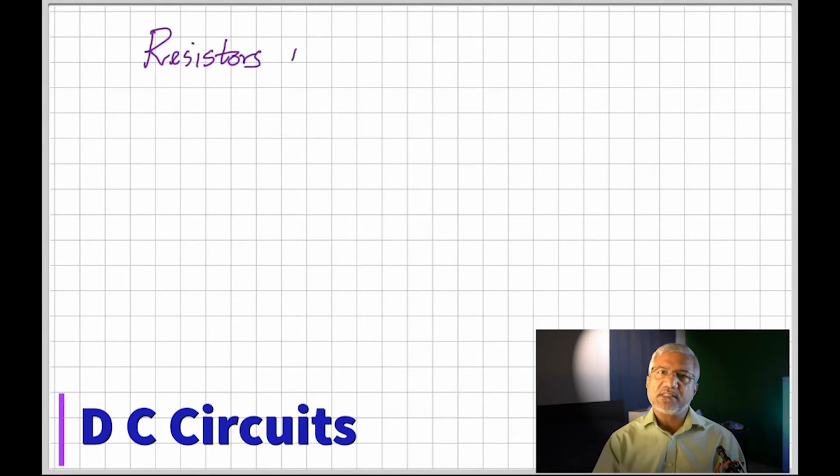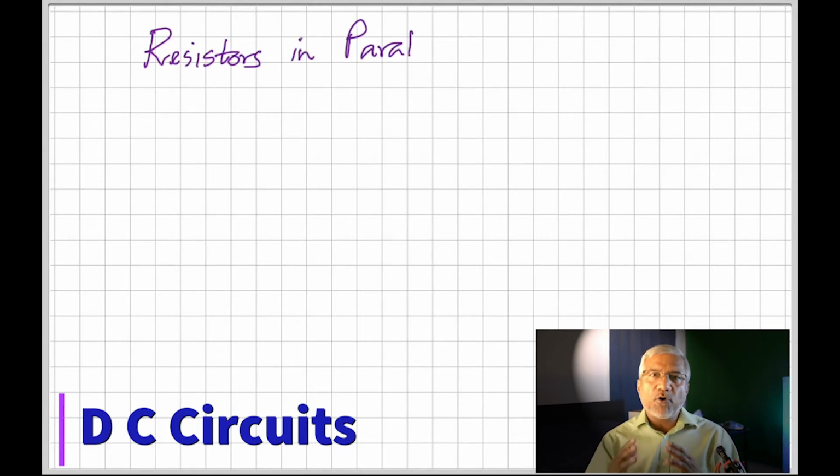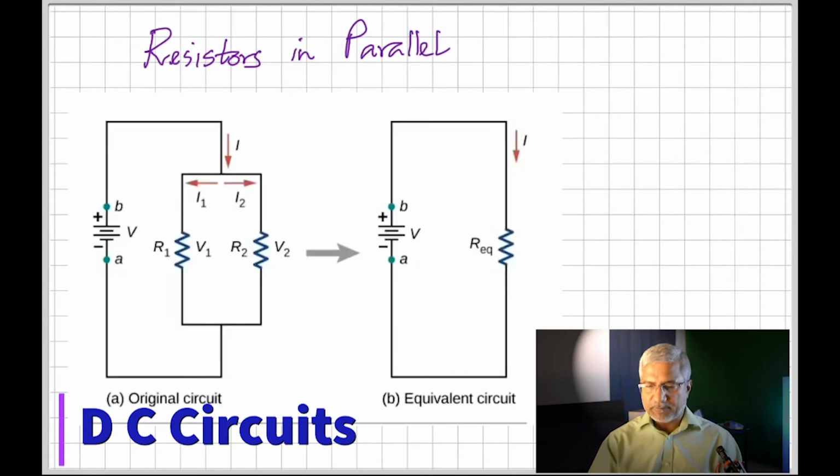When you put resistances in parallel, the voltage across them stays the same. And the reason is, here there are only two resistors connected in parallel, R1 and R2, and you can see that individually, these resistors are connected to the source. What does that mean? This is the positive terminal of the battery. This end is the positive of the resistance. So you see how it's hooked up there? And the negative of the source is connected to the negative of that resistance. It's the same with R2.